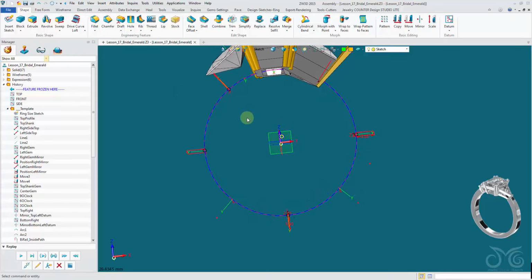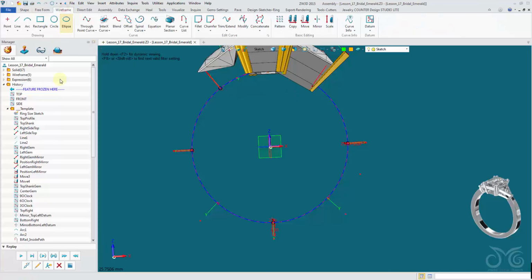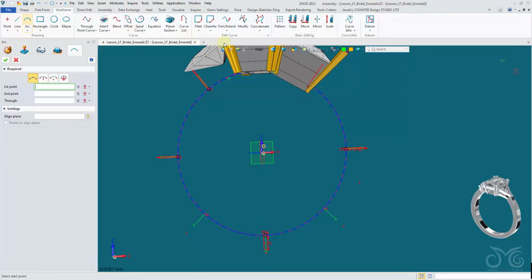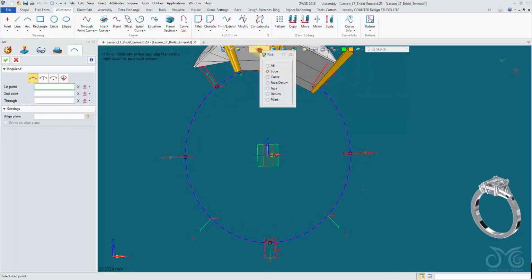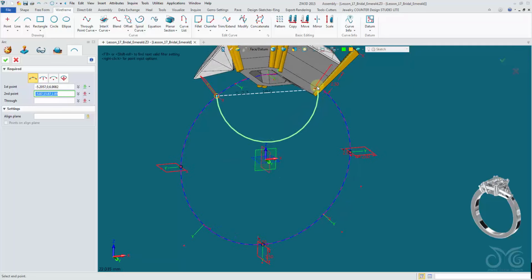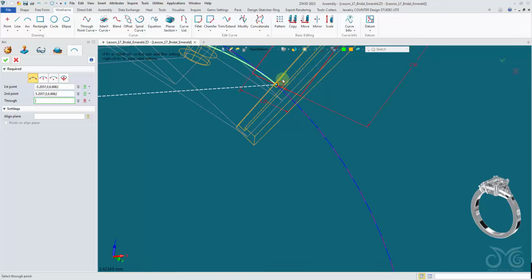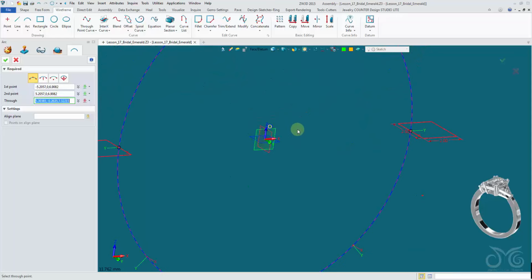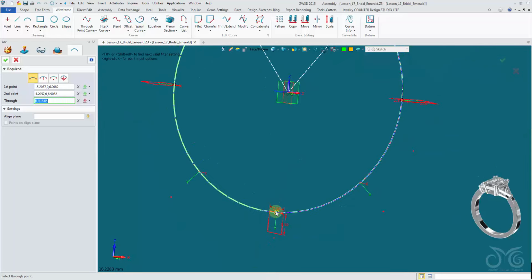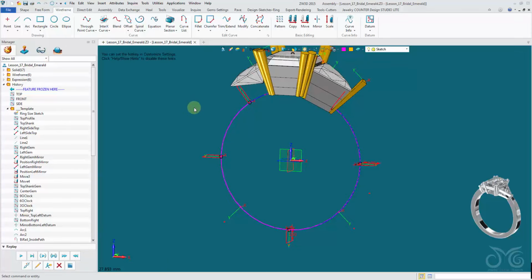Okay, now we need to insert a curve for our drive curve loft to loft about. Wireframe, we'll use the arc. I want to snap into here, so let's change my entity filter onto datum. Snapping to that datum. First point. Second point, I want it to be the datum in here. Yep, snapped in. And the 3 point is at the 6 o'clock datum. Let's make it a pink color. Confirm. Okay, so there's our arc.